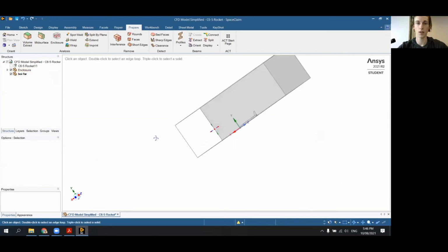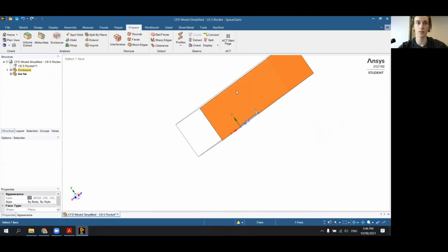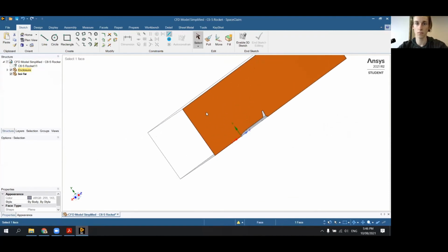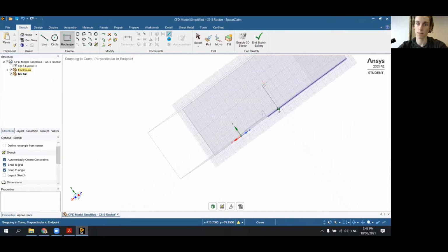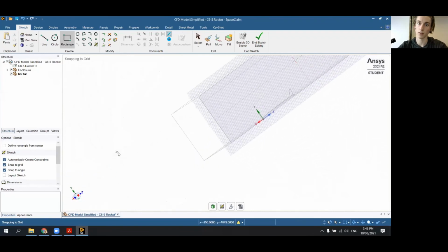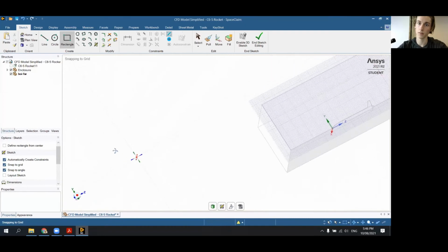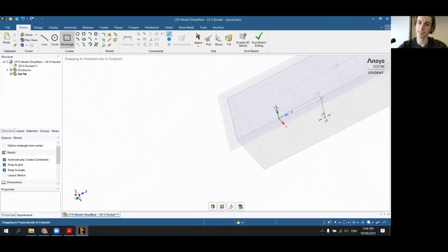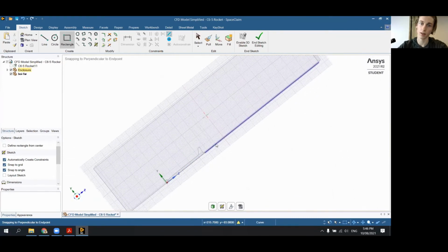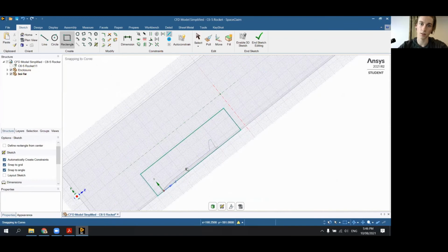All right. And then I'm going to rotate around. I'm going to select this face. And we're going to create a sketch on that face. I'm not the best at rotating the camera for these things. Forgive me. It doesn't have to be perfectly aligned because we're literally just drawing a rectangle anyway. But we might want to draw from, say, there to maybe there. Doesn't have to be exact measurements, but we want to include that wake region and we want to include the region sort of around.